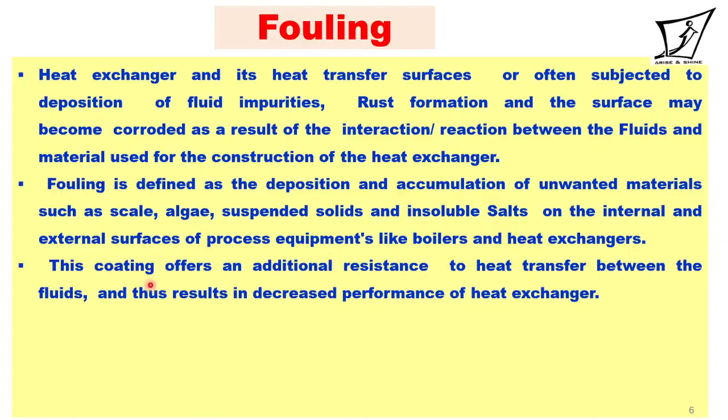This coating offers an additional resistance to heat transfer between the fluids and thus results in decreased performance of the heat exchanger. The scale or coating deposited is generally insulating in nature and it resists the heat transfer between hot and cold fluid, which ultimately decreases the performance of the heat exchanger to transfer heat between hot and cold fluid.